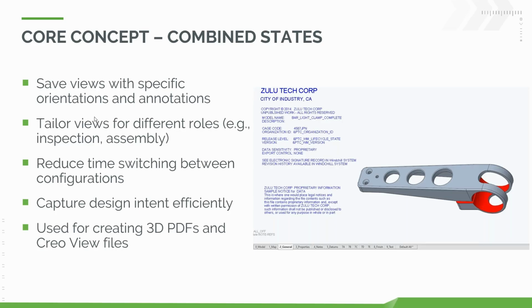So yeah, again, in all of these different tabs, let's just call them that for now, we can show different view orientations. So we can say, okay, this one's this view, the next one is going to be the front view, the next one is going to be the right view, and we can then show specific measurements, or we can show those measurements in 3D as well. It's up to us.